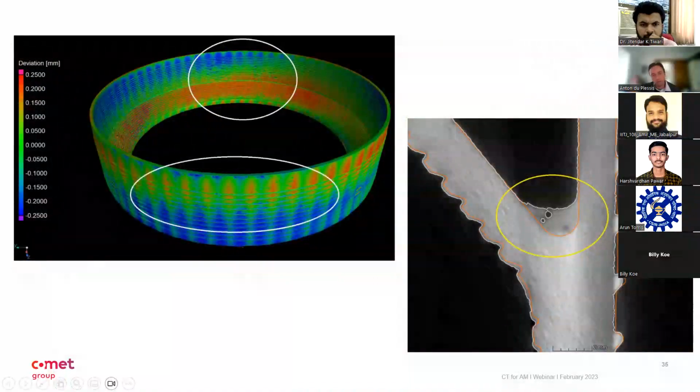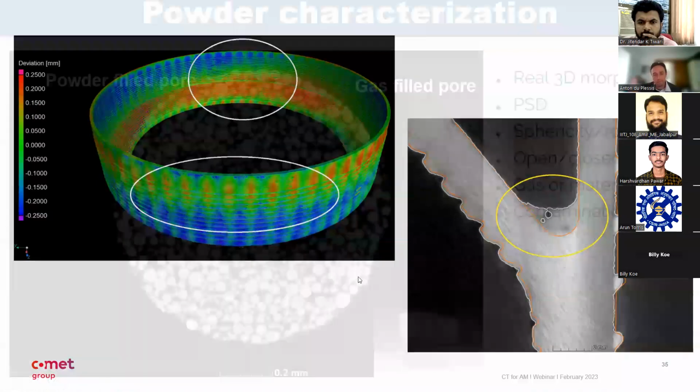And when you do that, you can evaluate, and you can see, as you've seen on the photograph, there are some surface pits, but they don't extend very deeply. And in the corners on this part, you see some unmelted powders with some pores inside, but that is not a problem for this application.